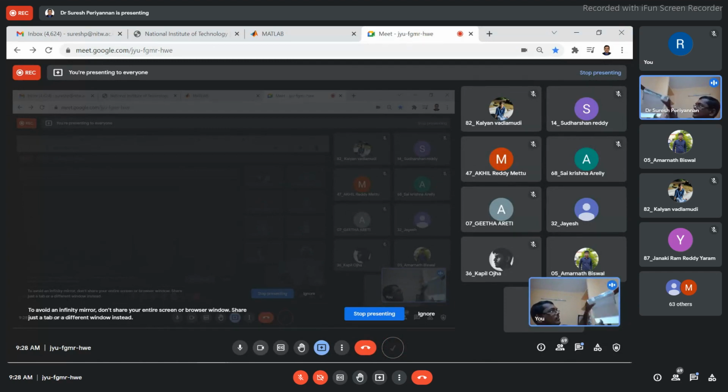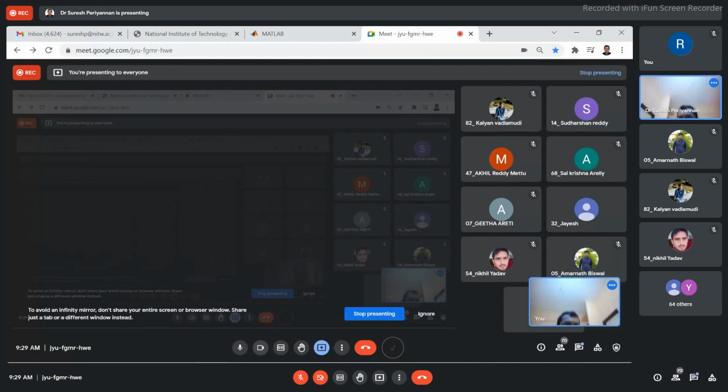Earlier it was vertical, the first case. Now I'm explaining this. The bracket is now like this. Now the distance between the point C and the load acting point here, then what will happen? This bolt is going to have a direct tensile load. When the load acts at this much distance, due to bending, each bolt is going to have a direct tensile load, I mean, each bolt is going to have a resisting force. That resisting force we are calculating. So now are you clear? That is also tensile. Yes, sir. Okay.